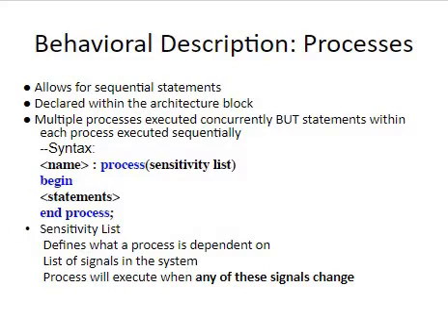That means that we may not be able to design sequential circuits by default by writing code inside a VHDL architecture. So in order to do that, we need to dedicate a particular portion of the code, and that portion is called a process. Whichever statements we write inside a process statement are executed one by one in a sequential manner. And that's how we implement sequential circuits or sequential machines using a process statement only.